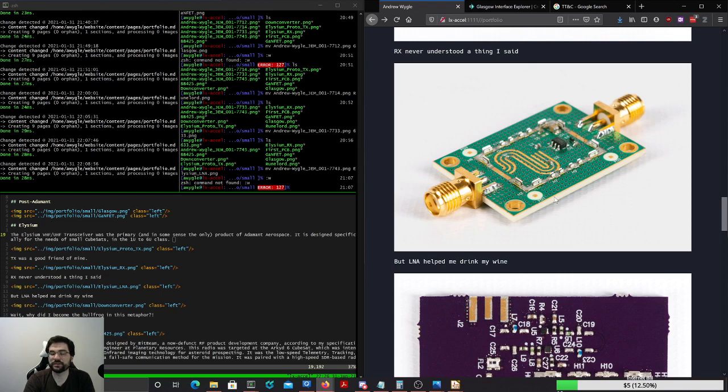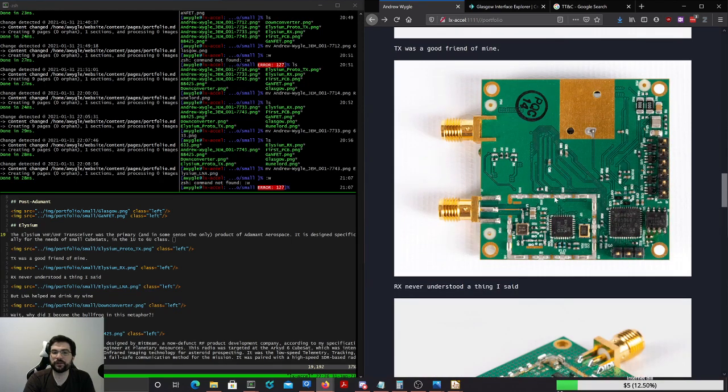How does FRAM work? I've never heard of it. So it's ferroelectric RAM, and it uses the ferroelectric effect of certain ceramics, which is like ferromagnetic for magnets. There are these little domains of charge, and if they are unpolarized, then that's a 0. And then if you can polarize them with an electric field, that will read as a 1. Reads are destructive, so you have to refresh it every single time. But basically it's the same physics with hysteresis as ferrites, except that it's electric instead of magnetic, so it can switch a lot faster, and it's a lot lower power as well. The real equivalent to core memory is MRAM, which is magnetic RAM, which literally is just core memory on a chip.